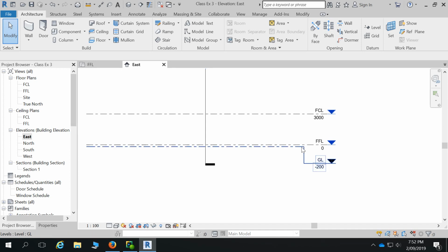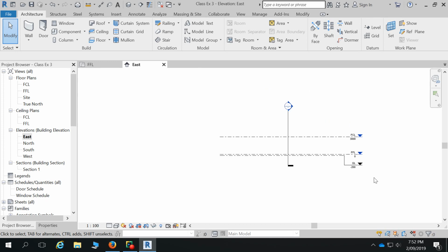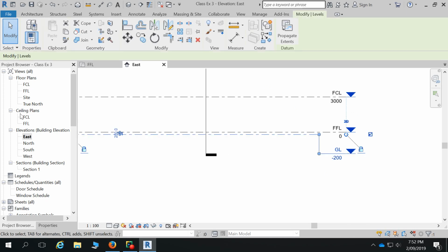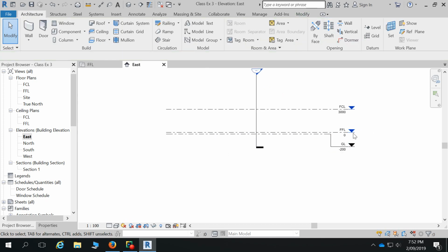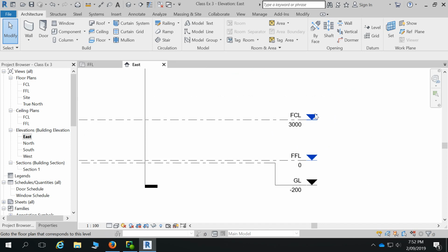Sometimes your levels are just so that you've got reference in your elevations, or reference so you can get to things, but you don't actually ever look down on those views. So you can make them not plan views if you want. The only way to do it is at that first instance by unticking that option. So it doesn't necessarily matter if you have or not, but it's just a way of simplifying these views that you're actually giving cameras. Anything with a blue head on your drawing, if you double click, goes to the view.